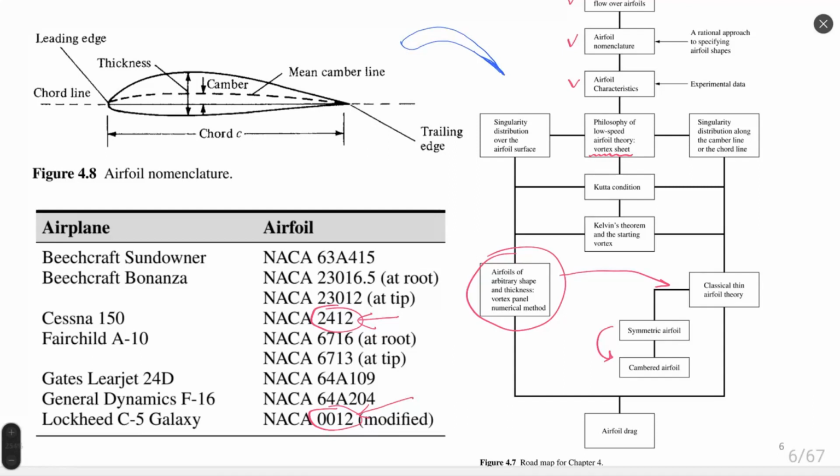But I think it is a very interesting question about the relation between thickness and curvature of a camber line. Highly cambered airfoils, I'm not even sure can be simply described by thin airfoil theory. Because thin airfoil theory, as Anderson says to us, can be applied only to airfoils where the velocity perturbation, or change of velocity between inlet and outlet, is relatively small with respect to the freestream velocity.